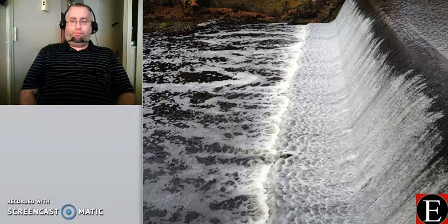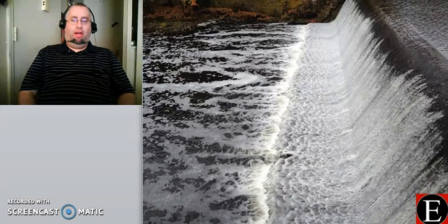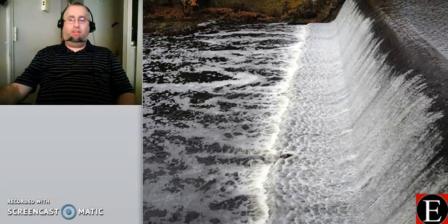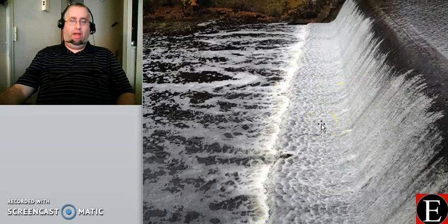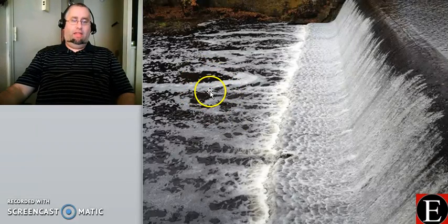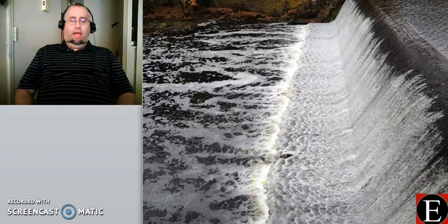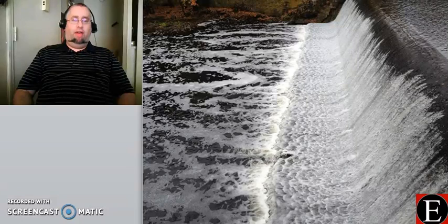Okay, so here is a picture of the spillway, and I'm going to talk about this in a bit greater detail, but what I want you to see is that there's essentially two regions of flow. Up here we have the fast-moving kind of wild river water, and it goes over the spillway, and then there's this very distinct barrier between the fast-moving fluid that's going over the spillway and the slow-moving fluid that is downstream of this transition point. This is one application to slow down river water as a river enters a village or a town.